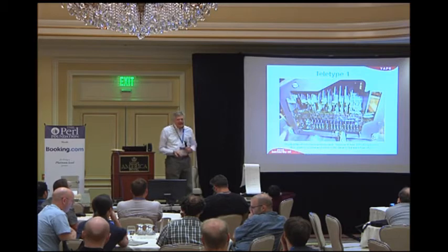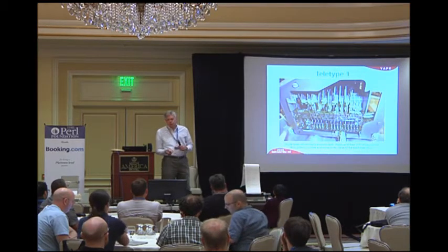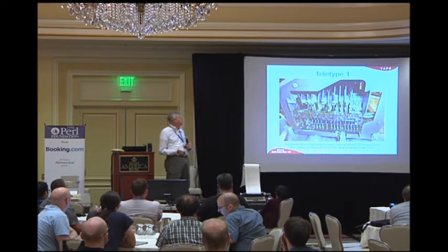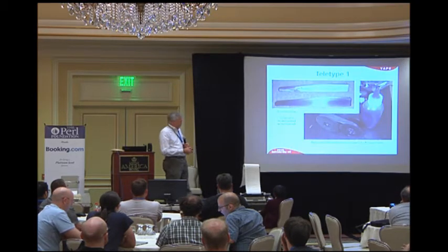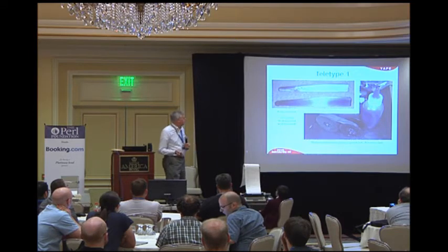Okay, so this is the side of the keyboard, and just to give you an example, this keyboard has over 100 oiling points. But you got to make sure that none of the oil touches in here because it will short out these circuits. So you got to be very careful what you're doing. These are the feet. Somebody decided they would spray paint it and just took all that off. I restored the ribbons by just re-inking them.